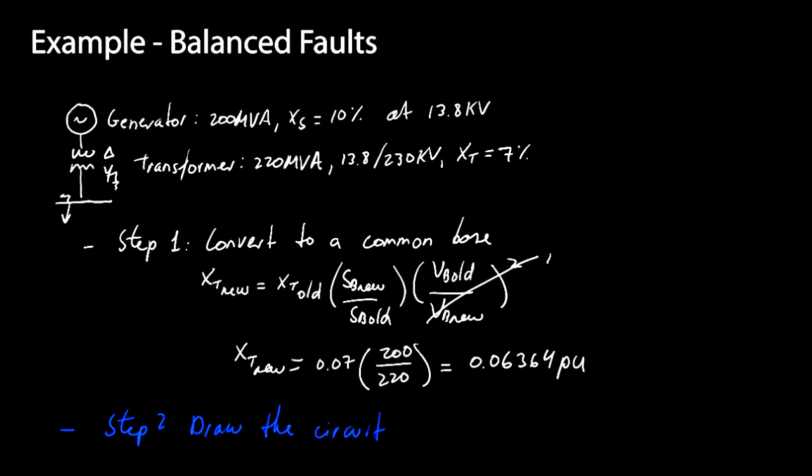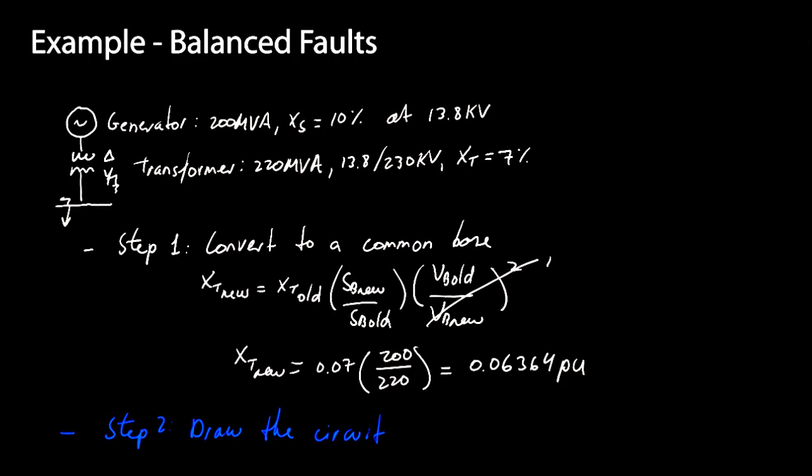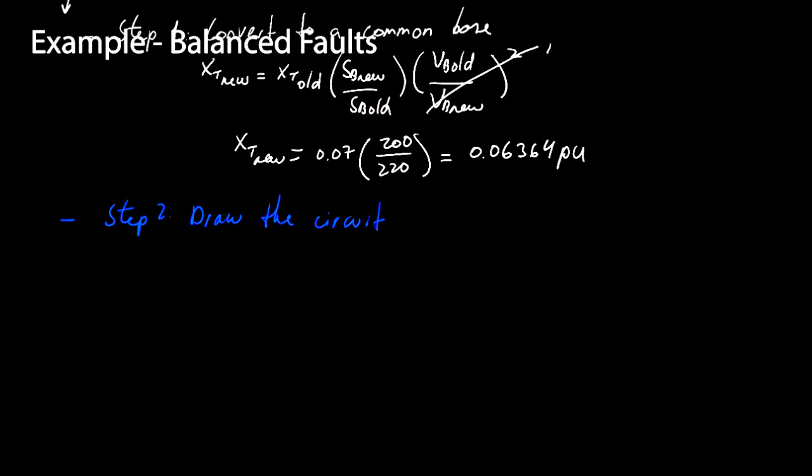So in this case, again, we have generators, so we have the synchronous reactance of the generator, then we have the transformer, and then we have the bus. So we're going to have only 2 reactances over here. So we have the system over here, which, again, we mentioned this before, is going to be at 1 at 90 degrees per unit, since we're taking the terminal voltage of the generator as the base, or rather as the reference.